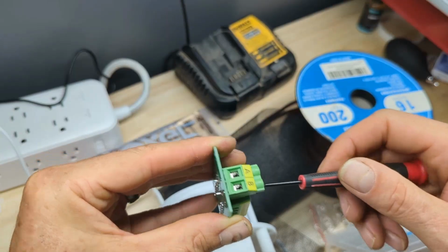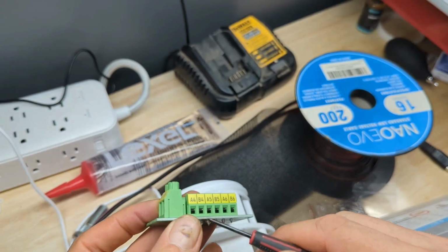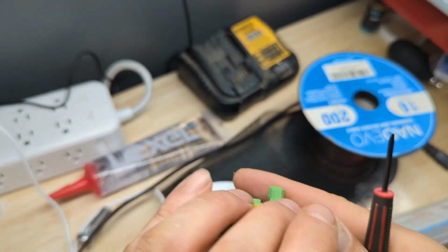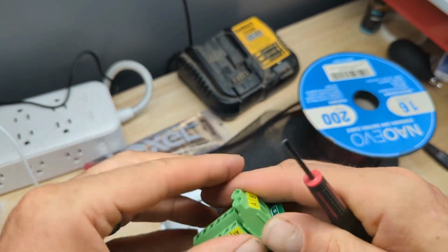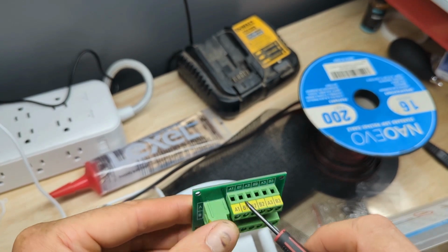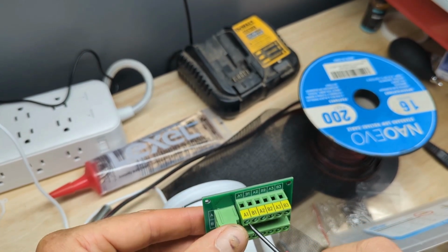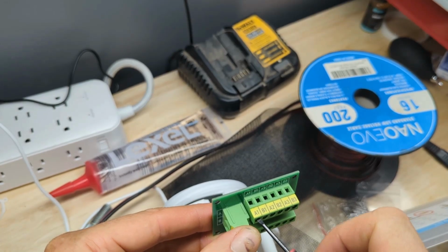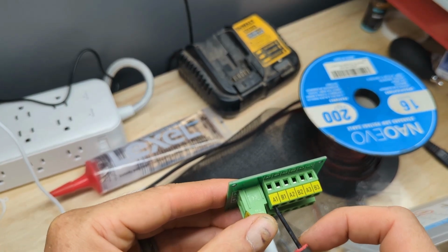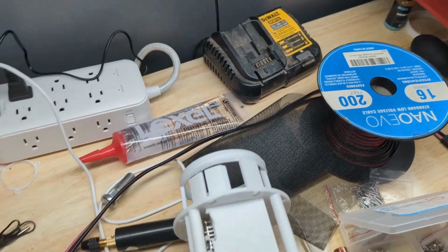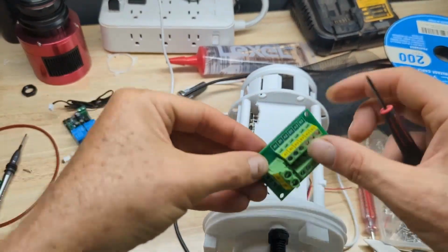So that's pretty much how, and that's the same concept of these ports on the side. So you have your A4, B4, A5, same way it's all labeled on each side. And you'll basically just tighten these screws on top to actually clamp the wire down. So turn clockwise to actually tighten it and clamp the cables in, and then turn counterclockwise if you need to release the wires.